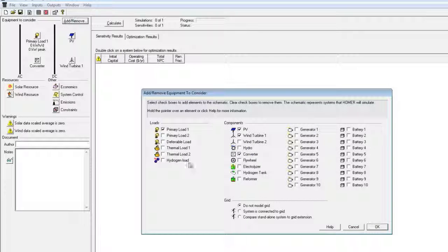And then the other thing you need to decide is whether you're going to be on grid or off grid. If you're going to go off grid, you need batteries, possibly a backup generator. As we are already on the grid here, generally people feel that it's best just to use the grid as your battery, especially if there's a purchase back for any surplus that you make. If you have batteries, you store the surplus and use it when you're not producing enough energy.